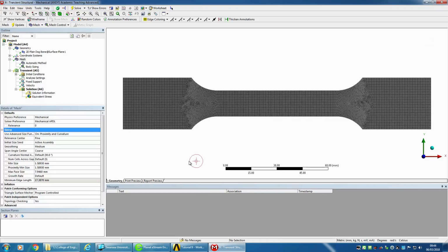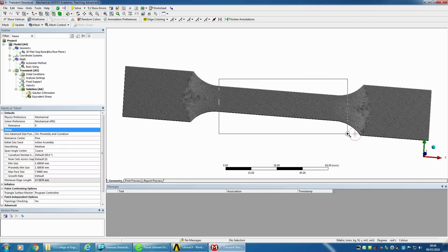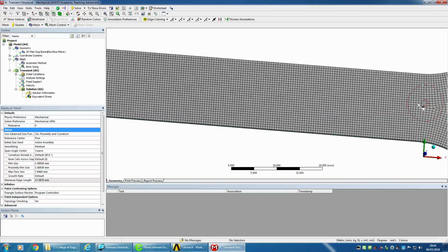Okay, the tabs are there just to focus the uniaxial stress down through the gauge section. So we don't really need to model what's going on around the fillets coming down into the gauge section. So we could actually shorten this and literally just focus on a rectangle around the length of the gauge length. And in that case, we can have a really good mesh.